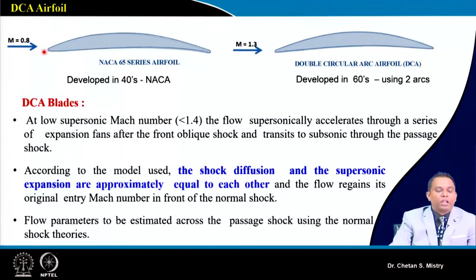What happens here, when my flow is moving on the suction surface, somewhere here maybe 40% or 50% of our chord, we will have our flow to be supersonic, because this is subjected to acceleration of the flow, and later on the deceleration of the flow when it is moving downwards towards the trailing edge.